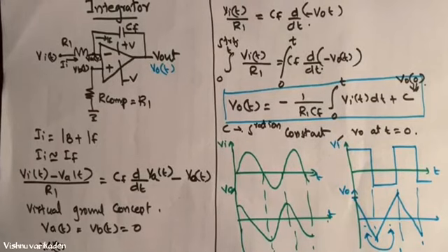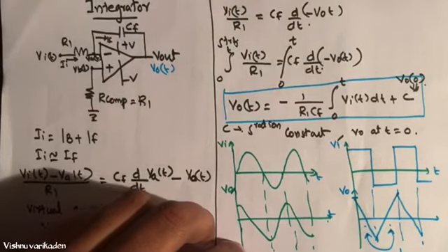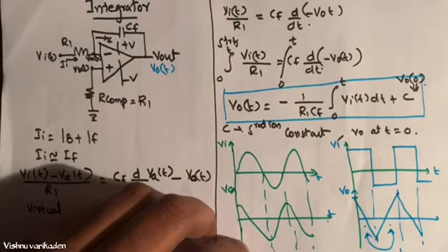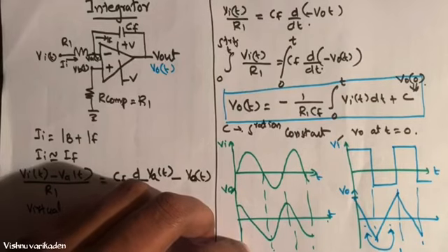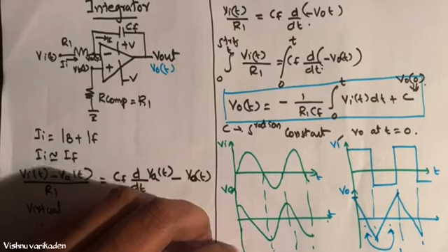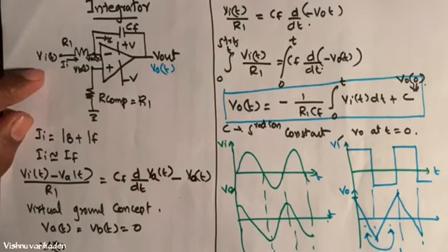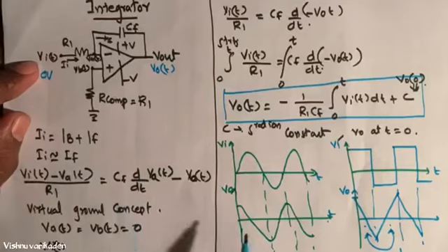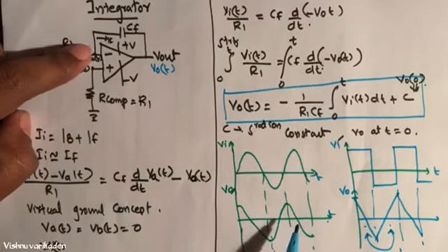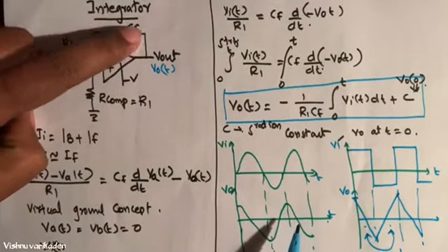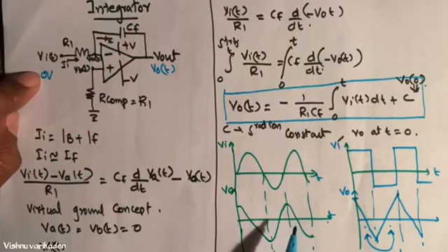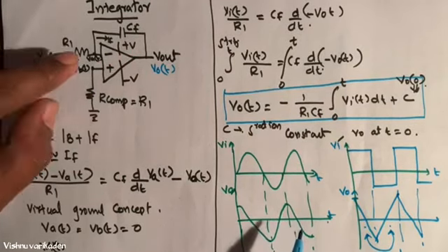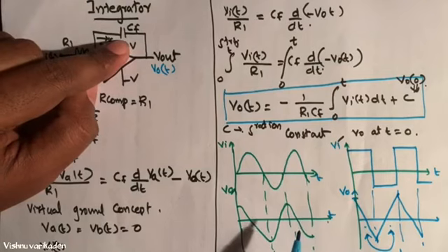So now we can find the frequency response of the ideal integrator and also the practical op-amp. In this general diagram, whenever the Vin input is 0 voltage, what happens? The capacitor is in the blocking condition, so the capacitor is in the open condition.